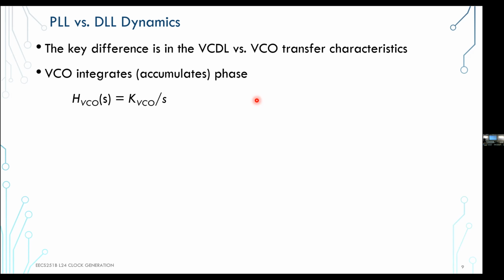So it's not going to be an integrator in a longer clock buffer chain, but it's going to be some sort of a low pass filter, because it takes some number of these noise sources and adds them up together. So it will accumulate, but limited. It's not going to be basically 1/s, and you're going to see that as we look at the transfer functions. But it's important to keep in mind, because post PLL, you will have some clock buffer tree, right?